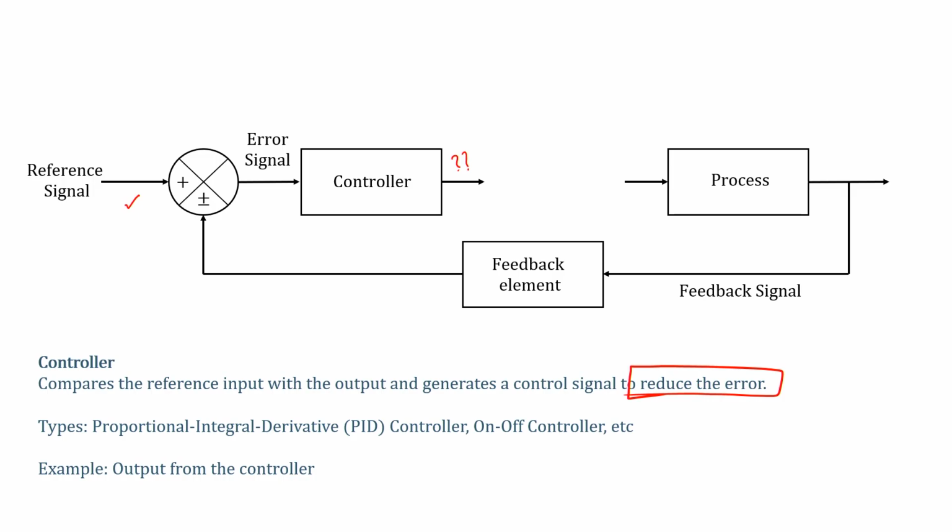Now what is the advantage in bringing down the error? If the error comes down, then your reference signal will be equal to the signal that is here. So for argument's sake, say suppose this is 1, there is nothing here. In that case this is exactly the output signal, right? This is 1, then the signal that is coming here and the signal that is coming here are both the same. So in that case the error signal is nothing but reference signal minus y of t. So if this signal goes to 0, that means r(t) and y(t) are equal, which means my reference and my output are the same, and that is what we wanted, right?